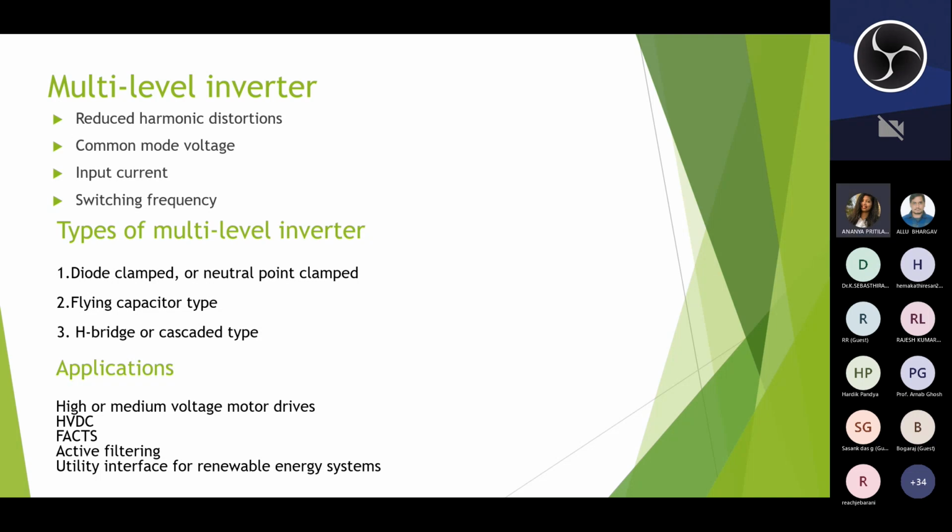It produces current at very low distortions. So it can operate at both switching frequency and fundamental frequency. By this, we can also go for reactive power control and selective harmonic elimination. By this technique, the THD can also be reduced.